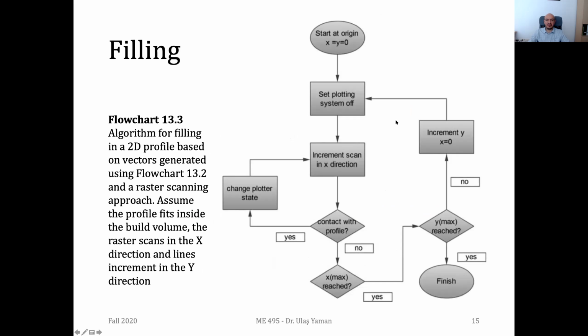This one, if you remember, is filling the interior with simply horizontal lines. And even not zigzag, but by doing some modifications, we can have a zigzag version of the same algorithm. But if you look at the CAM software of different types of additive manufacturing machinery, you will see that in addition to zigzag or just simple horizontal lines, we have tens of different filling patterns.